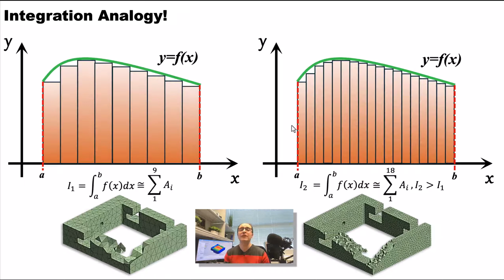So this is the same thing in finite element. In finite element, you can discretize the model into smaller pieces or smaller elements, but there is a limit. We cannot continue doing this forever. However, with small enough elements, we can actually get a really good accuracy in our model.